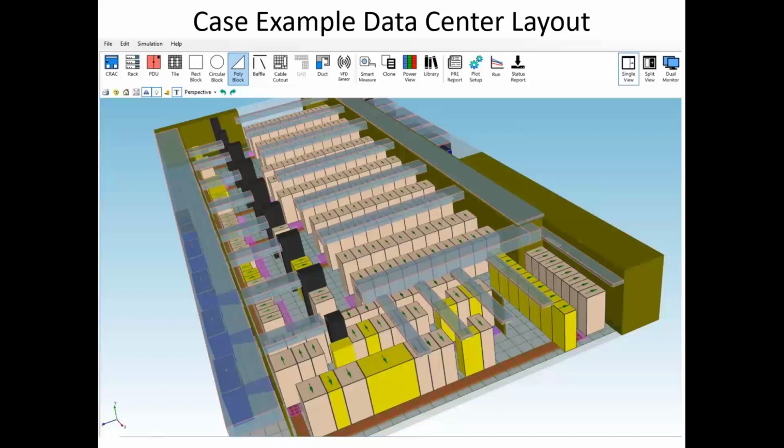It's dumping heat. There's a delta T. We're using a convective heat transfer equation to basically dump the heat across that server, or that rack. That rack is effectively a block with an inlet-outlet pair on it, a boundary condition pair, and we have on one side air coming in, the other side air going out. We do a function to dump the heat. That's how it works. Now, fidelity can be turned up, but of course you run into time when you do that. So for the most part, when you're looking at a data center like this, with this level of granularity, it's easiest to use a coarse level of representation for these racks and do it with average watts per rack.